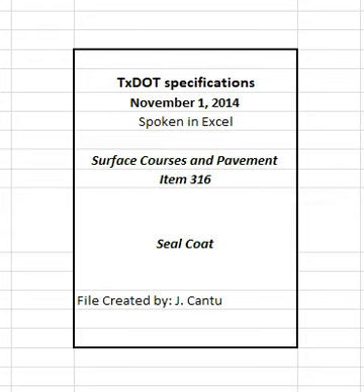4.8.3 Non-uniform application. Stop application if it is not uniform due to streaking, ridging, puddling, or flowing off the roadway surface. Verify equipment condition, operating procedures, application temperature, and material properties. Determine and correct the cause of non-uniform application. If the cause is high or low emulsion viscosity, replace emulsion with material that corrects the problem.